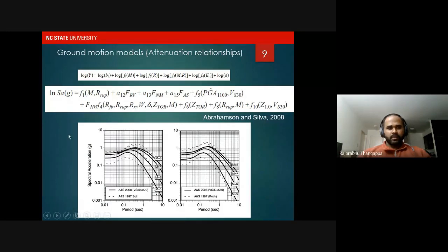So as we have these refined accelerograms, we perform the response spectrum analysis for those available ground motion records and perform regression analysis further to relate the ground motion parameter of interest.